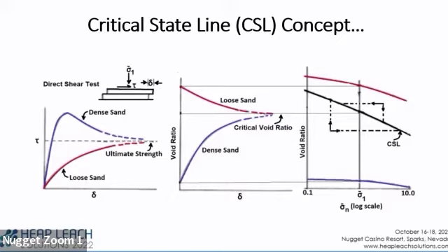But if it's dense and you shear it, they'll actually roll up and it dilates, it gets bigger. And that's pretty counterintuitive. You load material, this is principally shear loading, but you load material with, say, an earthquake or blasting or whatever, and if it's already dense, it's going to become less dense. So that's what this graph represents.